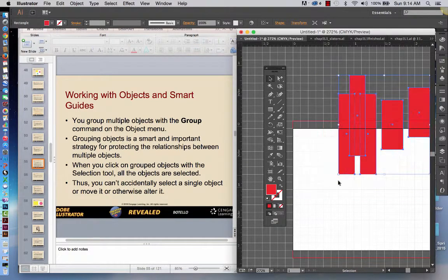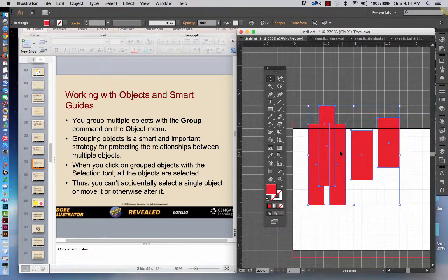They will edit as a group if you want to do a number of different things with them as a group. If you want to get just one of them out of that group, you get the group selection tool and you can select just one item. You can also double click, and that will bring up the remaining group as a grouped whole. Now the other selection tool that's kind of cool, if you click and hold on this, is the direct selection tool.